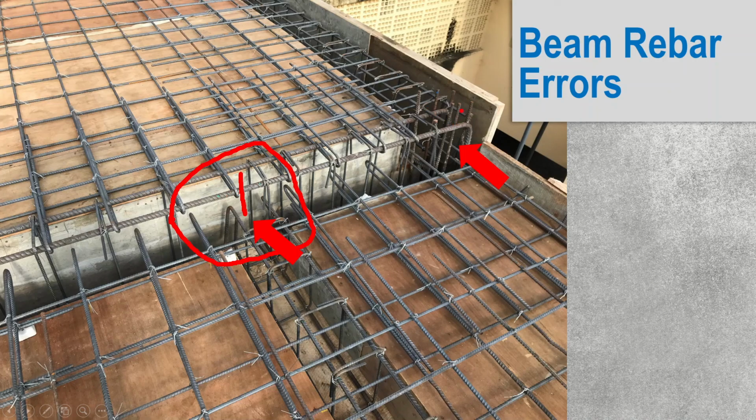Here you can see they have not anchored the top reinforcement correctly. The top reinforcement has only continued up to the columns, and beyond that they have not bent it into the column. That is a major issue in the construction, because when you have a beam connected to the column, there will be a hogging moment developed there. So if you have not provided the required anchorage length, there could be a failure of the column.